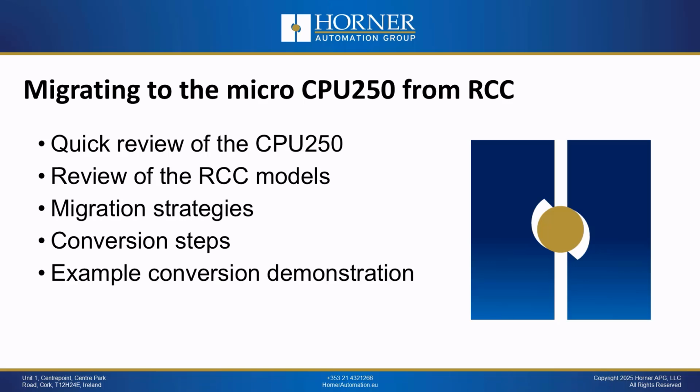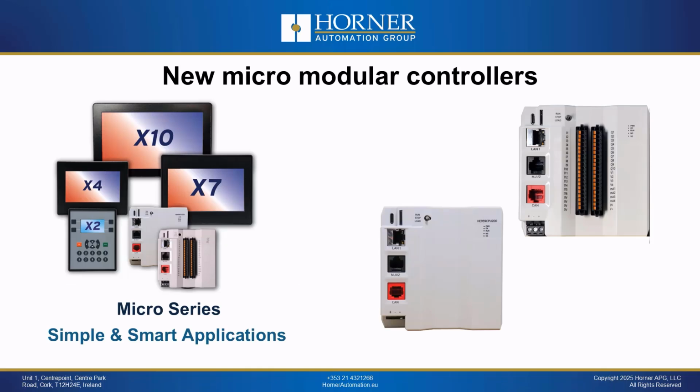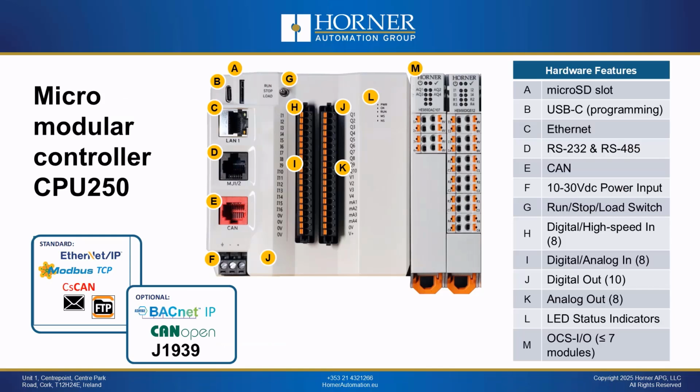The new micro modular controllers are one of the micro series, which previously only included all-in-one controllers and now includes modular controllers. Now these modular controllers are loaded with capabilities, lots of connectivity options with Ethernet and USB-C for programming and micro SD, lots of built-in I/O for the CPU 250 at least.